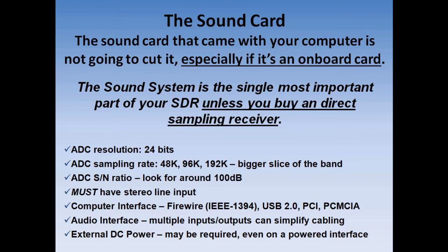Usually, it depends. It depends on how much power it's got into it. Usually you need independent jacks. I had to have 4 inputs and outputs to run this 940 off this LP-PAN adapter. So you need stereo in, stereo out, because the I and the Q have to be handled individually.